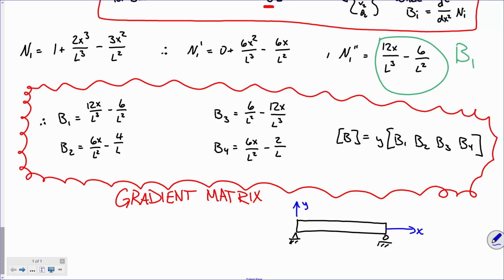The reason why, no pun intended, is if I go back to look at a stress vector, what does bending stress look like? It looks something like that. And then we measure that stress from the centroid and we say Y is that distance. That's a great question. What is Y? It is from the centroid measured up or down. Because remember, bending stress gets larger from the centroid. And it's the distance Y.